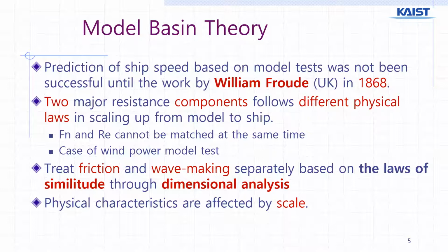When we measure motion of the system in waves, we follow the Froude number scale. But the propeller wind power generation follows the Reynolds number scale. So we cannot match both of them together with the same model. That is a similar problem as this.